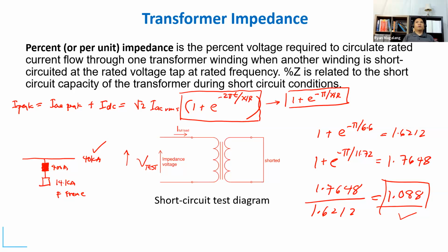Go for Eaton or Square D. They have tables that show this size of fuse or breaker works with this size of current limiting fuse. And there's a ratio, let's say 2-to-1 ratio, 4-to-1 ratio. So that is something that you can do.